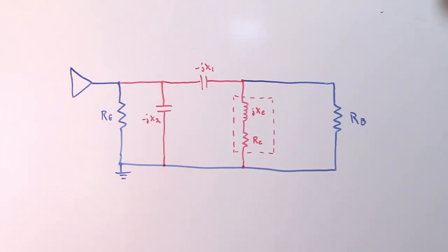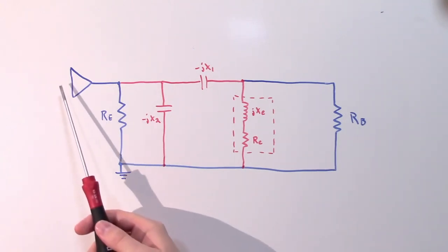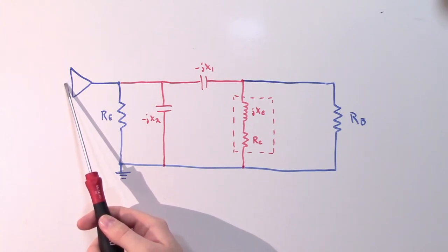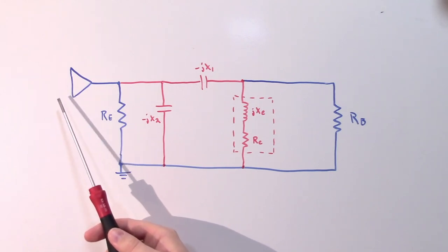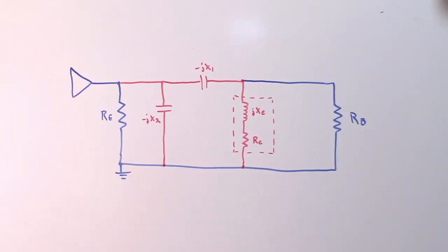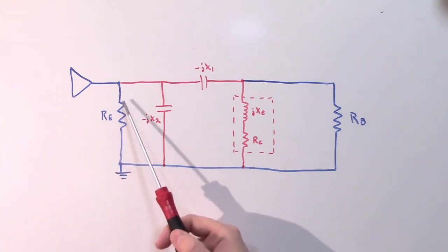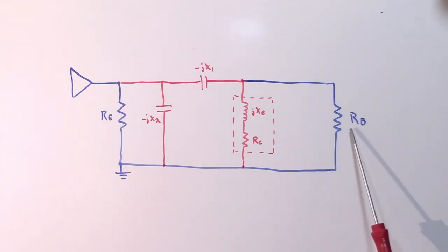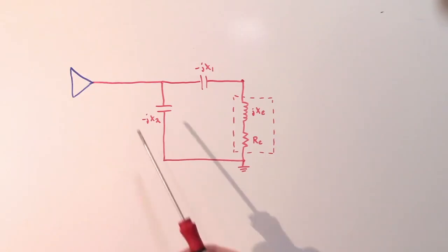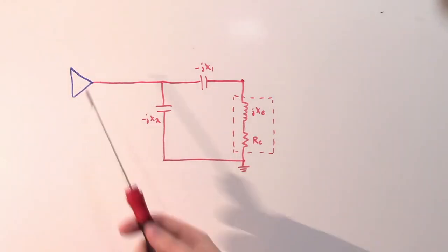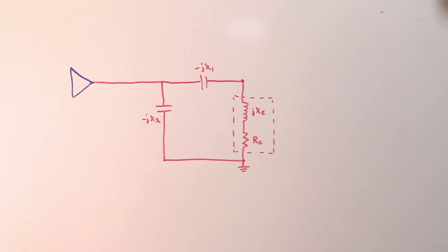However, we usually want the input of the amplifier to be a very large impedance, so that we present a very high impedance load to the crystal, so that we don't load it down and we have a nice high loaded Q. So usually the emitter resistor is large and the input to the base is large as well. So to simplify the analysis, we can just ignore those, leaving us with just the feedback network as the load presented to the emitter of the amplifier.